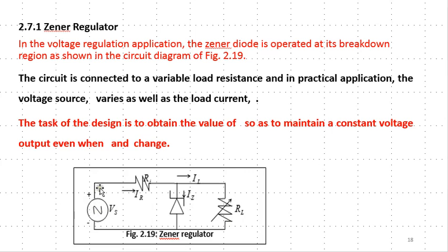We have our source of the voltage, and we connect this Zener diode across, that is, in parallel to it. The reason why we connect it in parallel is that whatever is the voltage across this diode should be equal to the voltage across the load, because if two things are in parallel, they have the same voltage, and this is the resistor that controls the amount of current flowing.